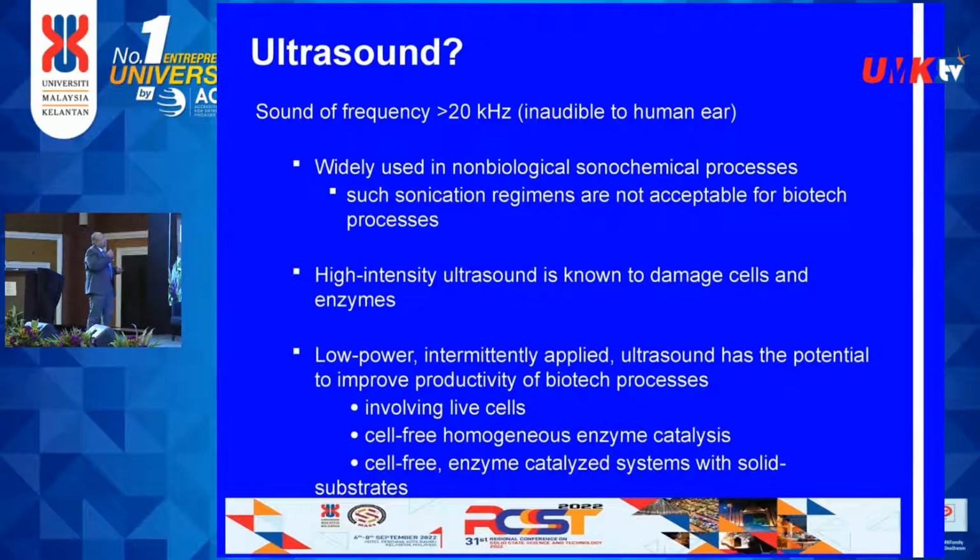How can ultrasound improve the bioprocesses? This is based on the possible mechanisms at constant temperature of operations. First, enhanced gas-liquid mass transfer, for example, for the aerobic fermentation, which is the biomass and ethanol production by K. marxianus from lactose. Second, enhanced solid-liquid mass transfer, in enzyme systems involving solid substrate, for example, the hydrolysis of insoluble cellulose by cellulase.